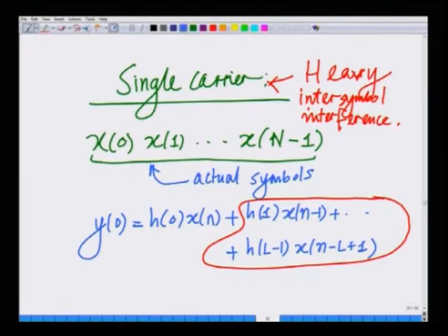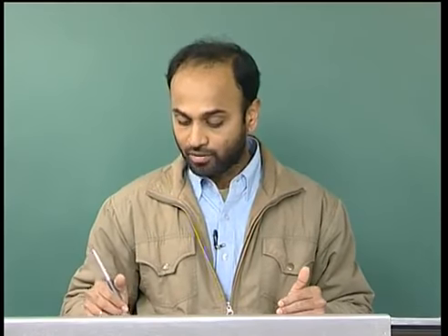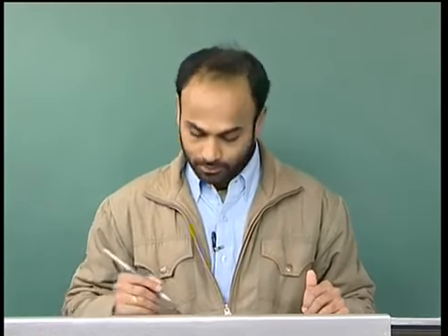This is very advantageous, since in the absence of OFDM, we have inter-symbol interference, where each symbol in the time domain xn is interfered by symbols in the previous. By adding the cyclic prefix and combining it with the multi-carrier IFFT/FFT operation, we have removed the inter-symbol interference and converted this into a flat fading channel at the receiver across each subcarrier.